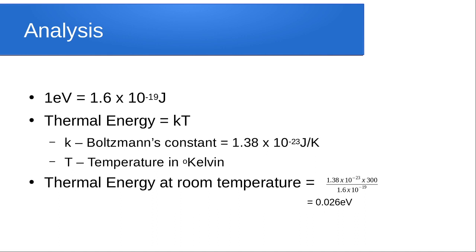So if we are using pure semiconductors, we need to increase the temperature in order to have electrons excited and moving from valence band to conduction band, which is not possible normally. Our devices that we use are working at room temperature. So we need to find an alternative for having electrons in the conduction band. That we will see how it is being done in a later part of this video.